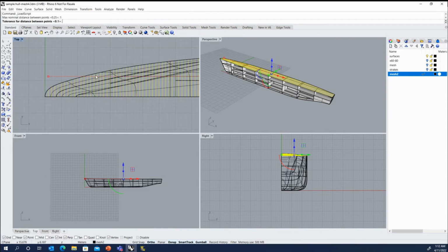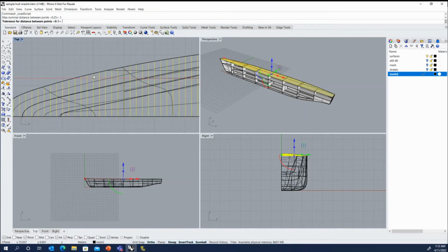When it goes to create points along this curve, these curves are not all in increments of 1 meter in terms of total length. So there's going to be a little leftover at the end. So this tolerance is what do I do with the leftover? Basically it's saying that if that last point is less than 10% of my spacing, don't bother adding an extra point, just make the last segment a little longer. Basically the last segment on the curve can be up to 10% larger than the selected spacing. If it's any larger than 10%, then go ahead and put another point in there.